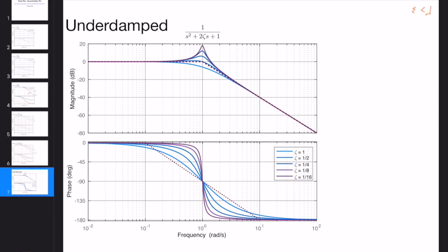Okay, so here, in order to show the big picture or the problem, I plotted the underdamped Bode plots of this system. Okay, so as you can see, omega n is equal to 1 radian per second for both cases. And as you can see, the cutoff frequency for all cases is happening around this frequency. So it's not the exact cutoff frequency, but the corner frequency, let's say. Okay, this is 1 radian per second. Okay, so if I change omega n, I would technically shift everything on the horizontal scale. Okay, good. So let's look at the results.